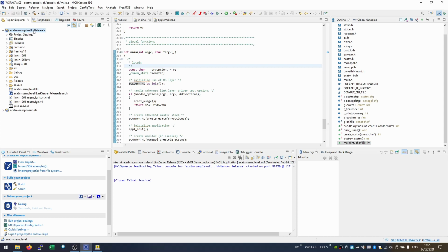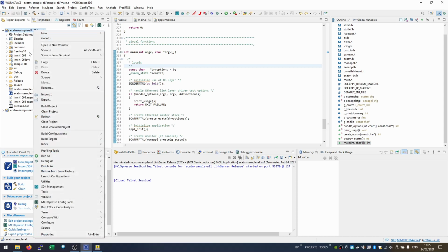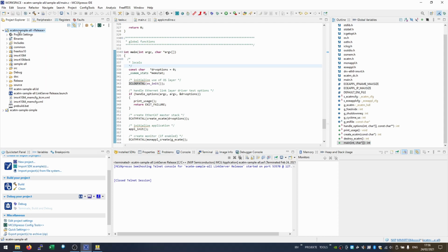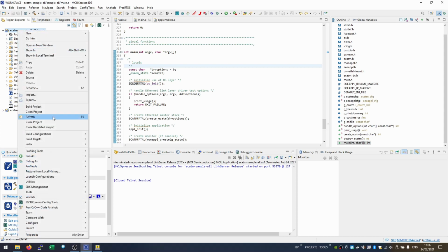This can be simply done by changing the properties of the project. But take care, if you change the properties of the project, ensure you remove the write protection from the project file. If you do not do this, this can lead to problems within the configuration of your project. So first remove all the write protections, then modify the project settings.